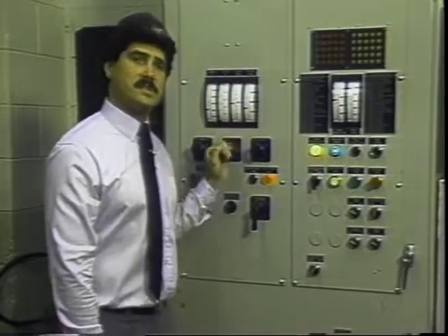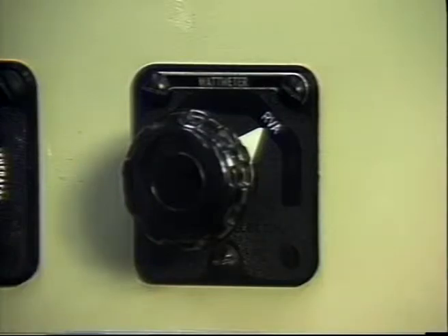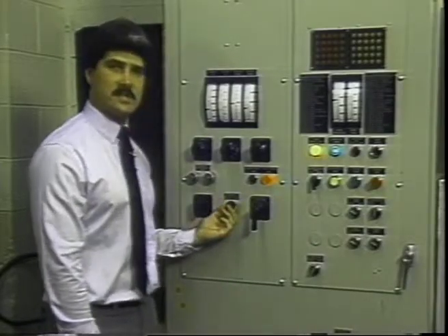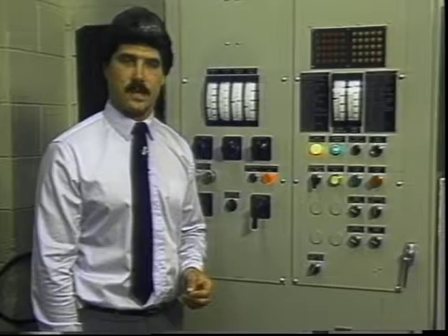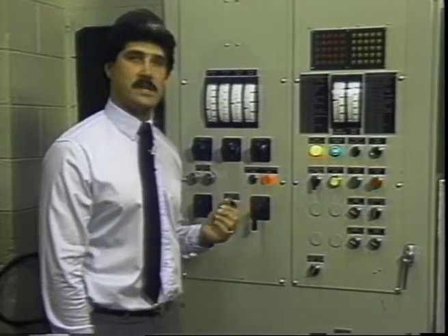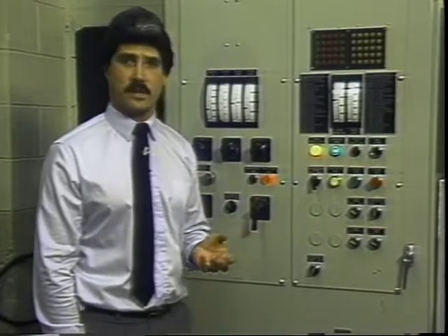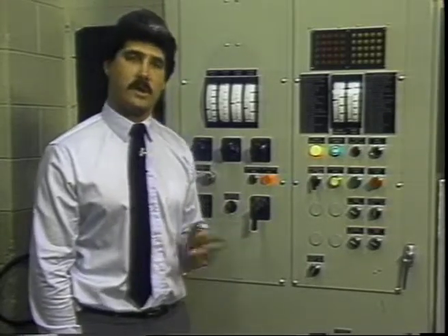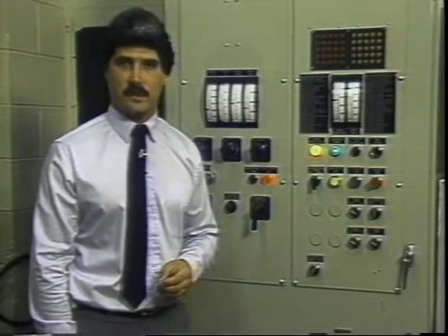Now, position the same selector switch to read kVARs. Any needed adjustment to kVAR load sharing can be done by adjusting this voltage adjust rheostat. At this time, this generator package is operating in parallel with one or more other similarly governed generator packages. You should periodically walk around the package to look for any visible signs of malfunctioning equipment. Refer to your operation and maintenance instructions manual for your particular recommended operational checks.